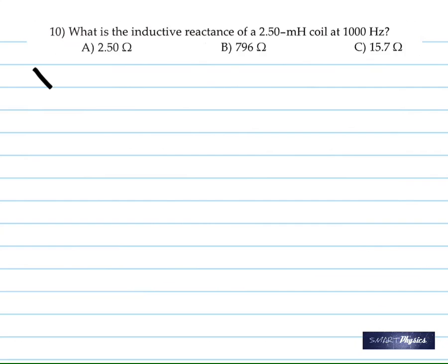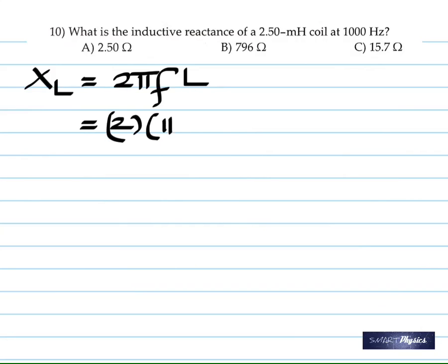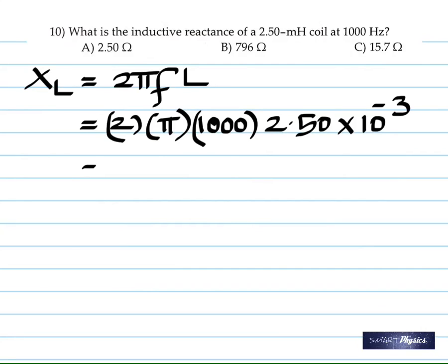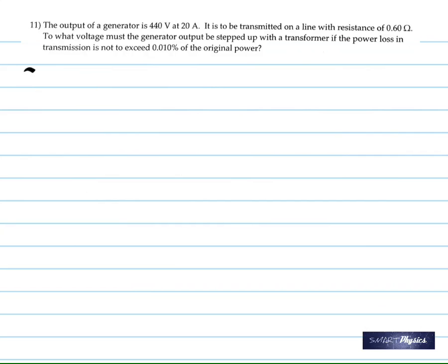0.72 ampere. What is the inductive reactance of a 2.50 millihenry coil at 1000 Hertz? Direct question, just an application of this formula. (15.7 ohms).